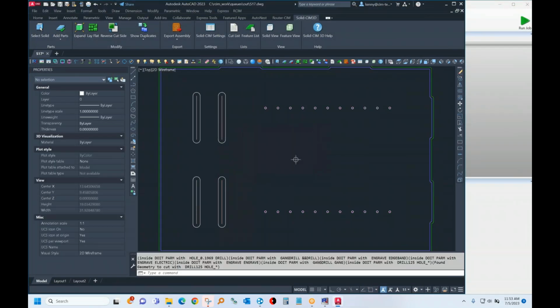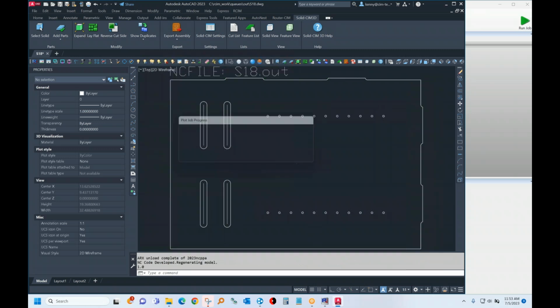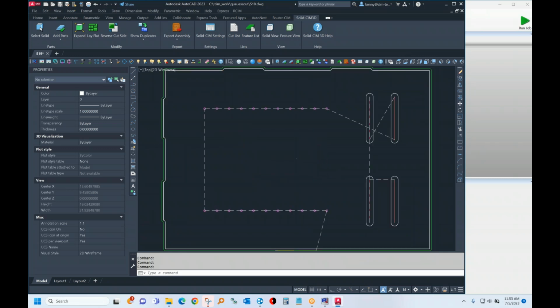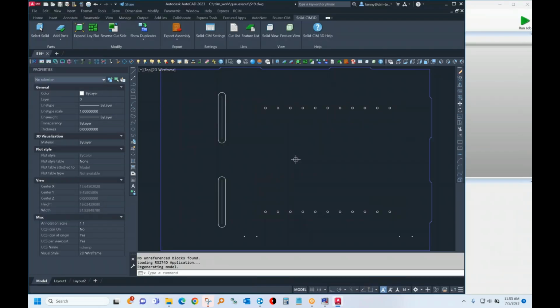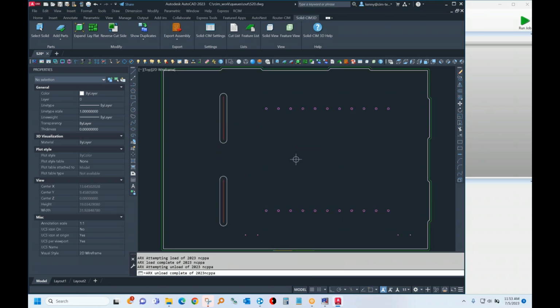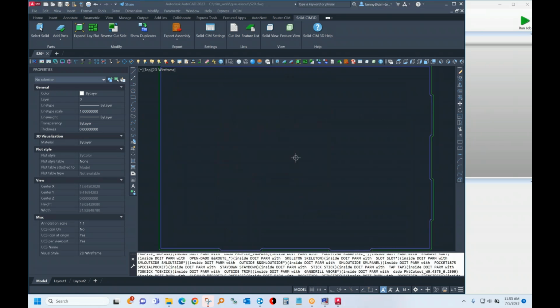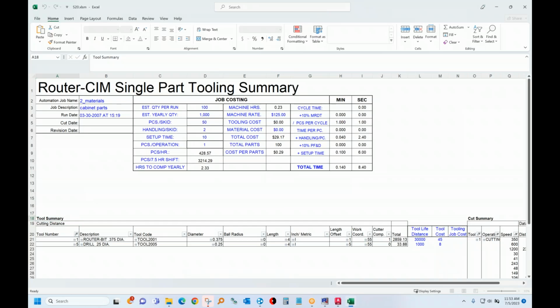You can emboss a symbol in SolidWorks. You can emboss a little arrow on the part, and Solid-CIM will know to rotate the part to that angle, whatever angle you had set on that little arrow. It also chooses the side to face up based on the side that had the most machining volume removed, which means if you had dados on one side and counterbores on the other, the dados would probably remove more material than the counterbores, unless you had a lot of counterbores.